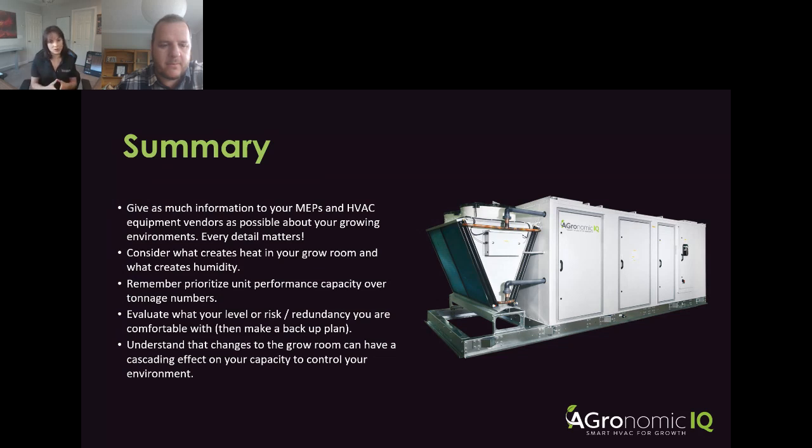Consider when you're going through your grow rooms, like I said, consider what is creating heat in the grow rooms and consider what is creating humidity, and kind of convey both. Like, hey, these are all of our heating applications and these are all of our humidity causing applications. Remember to prioritize performance and capacity over tonnage numbers. So if two equipment vendors are coming and saying, hey, we both have two 70-ton units, make sure that the performance at your conditions is meeting what your load is, because it's not always an apples to apples comparison when it comes to those kinds of outputs.